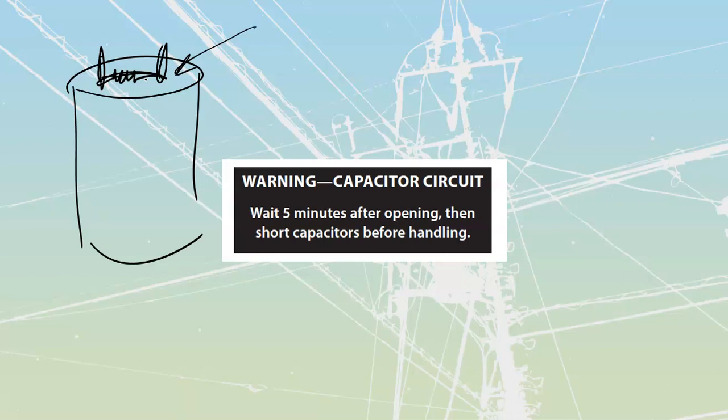As far as sizing for your capacitors, operate them correctly at their rated kVARs. If a capacitor has a different frequency listed on it, such as a capacitor rated for 50 hertz because it's European, and you use it on an American 60 hertz system, it is going to completely change the kVAR rating. You cannot be doing that. Use them at the proper voltage and the proper frequency.